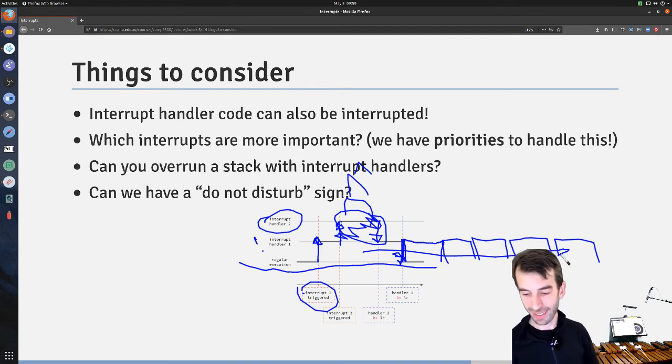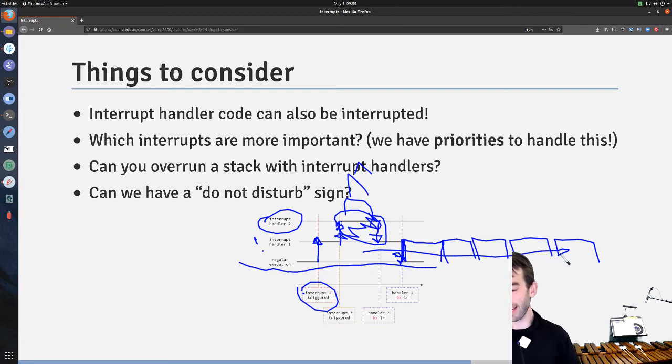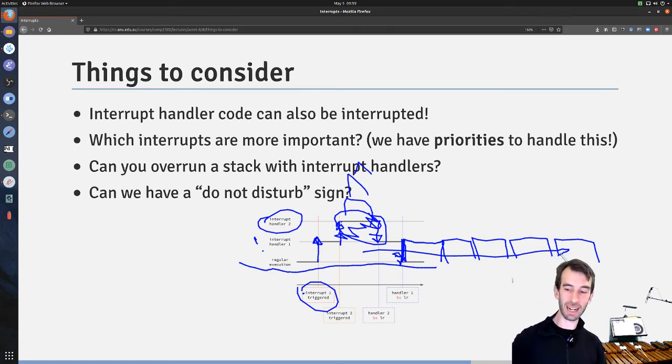Someone asked, if the memory is near full and there's an interrupt, how would the system handle this? I think it would just crash, yeah. On your disco board currently, we could probably do some kind of experiment to find out exactly what happens if you're in that situation. Like by setting the stack pointer to be at 0x2 followed by 7 zeros, so the bottom of SRAM, and then calling an interrupt on purpose, we could be in trouble. Maybe we'll try that later.